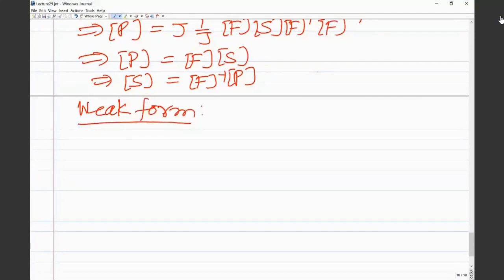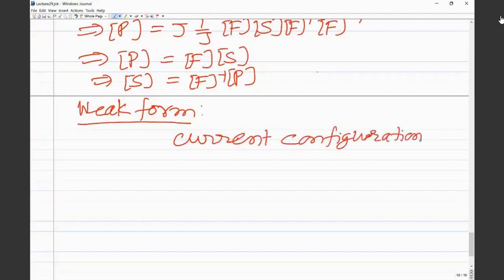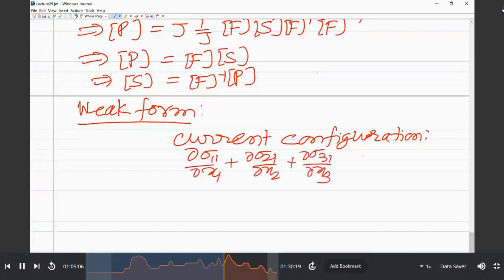So you would have derived the stress equations of equilibrium in terms of Cauchy stress components. The equilibrium is actually studied in the deformed configuration, or the current configuration. Let me write it in the expanded form. So del sigma 11 upon del x1 plus del sigma 21 upon del x2 plus del sigma 31 upon del x3 plus body force in the current configuration FB1 is equal to 0.